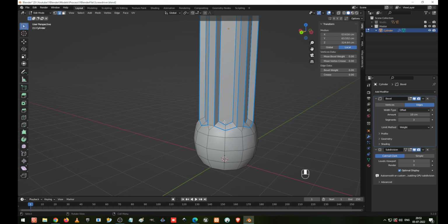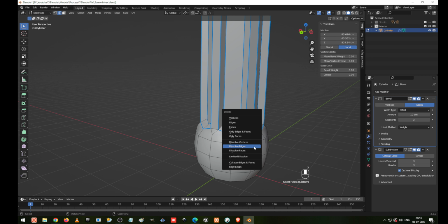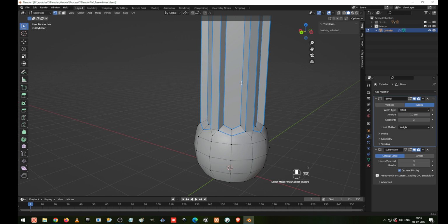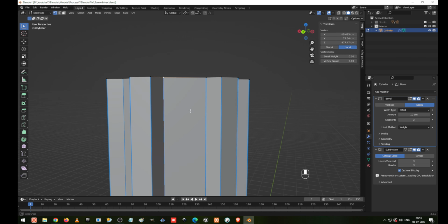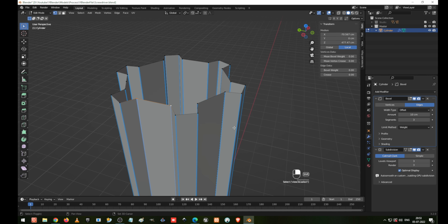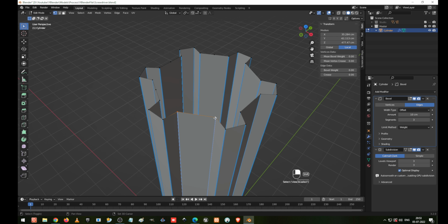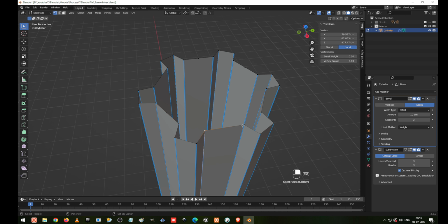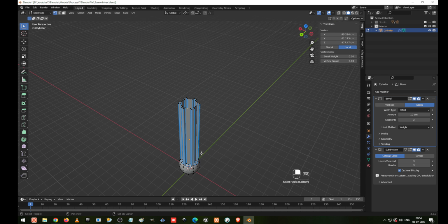Okay, so we can do one thing. A better way to make it look great: go to the edge selection. I press 2 and dissolve these edges, and go to the vertices selection. Before that I am going to create a subdivision. To create one edge here, right click, subdivide. I select this thing, press Shift R to repeat the same. I am subdividing the vertices in between to create new edge loops manually.